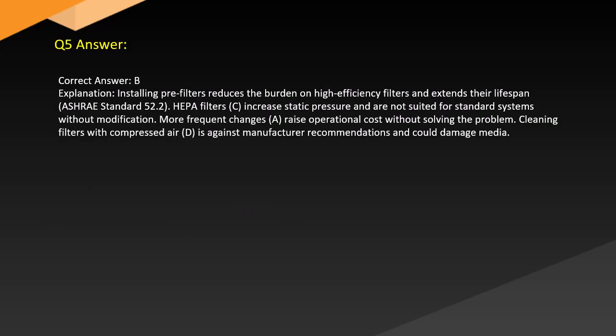Answer. Correct answer: B. Explanation: Installing pre-filters reduces the burden on high-efficiency filters and extends their lifespan. ASHRAE Standard 52.2. A. HEPA filters increase static pressure and are not suited for standard systems without modification. C. More frequent changes raise operational cost without solving the problem. D. Cleaning filters with compressed air is against manufacturer recommendations and could damage media.